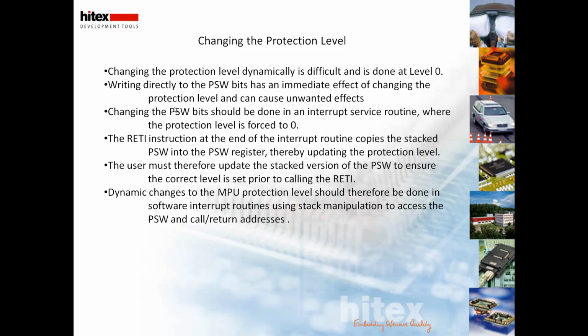By pushing items onto and popping items from the stack, we can get access to the current value of the PSW word, and as soon as I execute a ret-i, that modified version of the PSW word is popped off the stack and into the PSW register. So that means we can dynamically change the level by careful manipulation of the stack and the PSW that's contained on it.